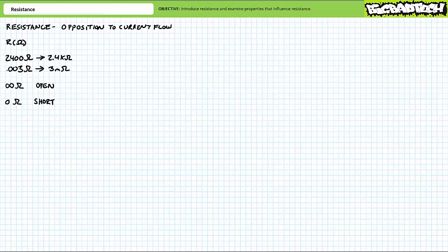These two extremes represent special case scenarios so important, we're going to give them their own identifying terms. A path or device with infinite ohms of resistance is called an open. A path or device with 0 ohms of resistance is called a short. An understanding of opens and shorts, and the important differences between them, is critical to your success as a technician.